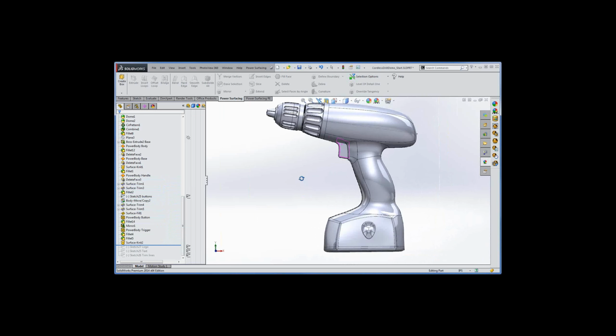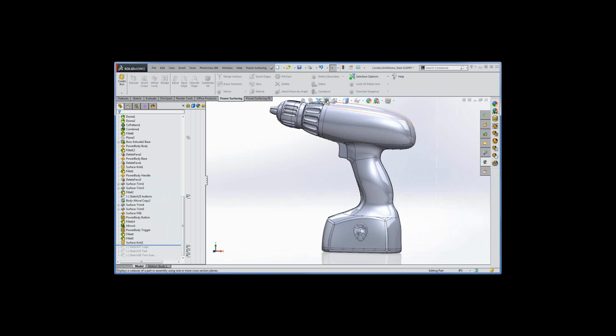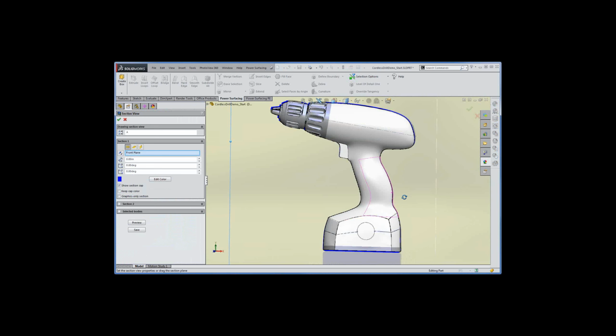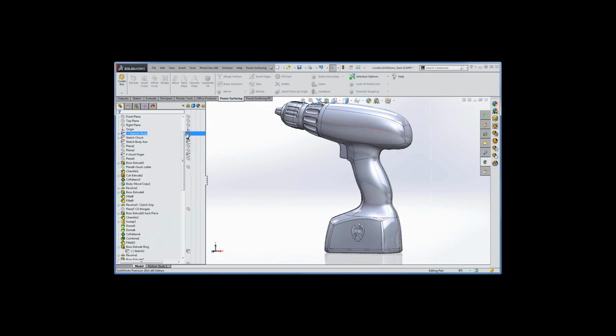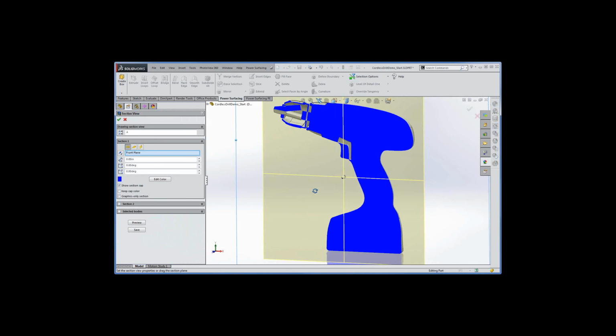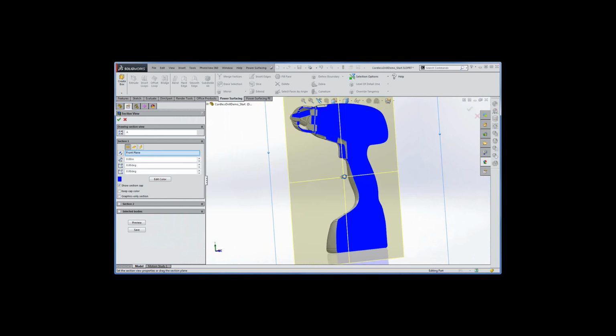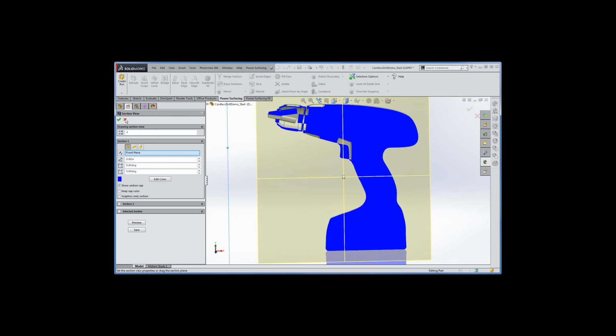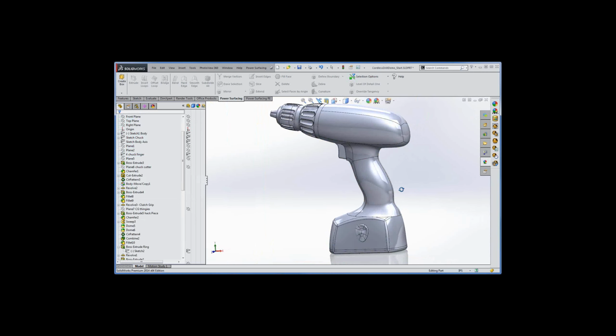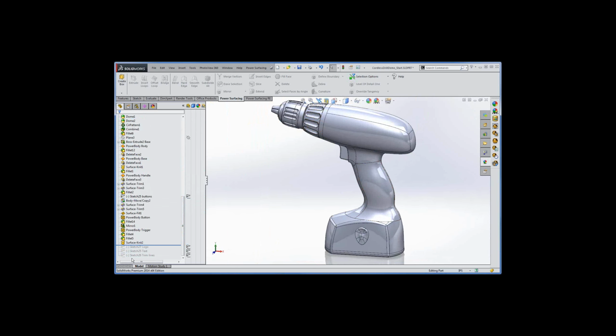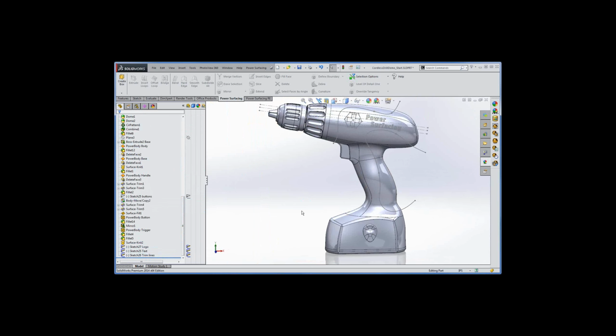Okay, so now my object is all put together, and let's check on surface here. Oh, one thing I need to do first is good time to turn off that sketch. And there we go. So you see it's all been knit together into a single piece. And at this point, you could then add more of your regular SolidWorks stuff. I've got some sketches in here ready to do all the fancy stuff, but I'm not going to bore you with that.